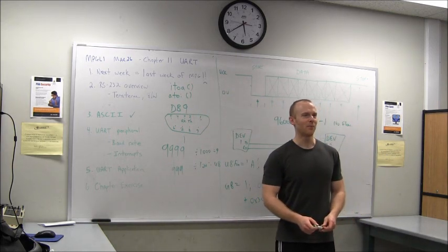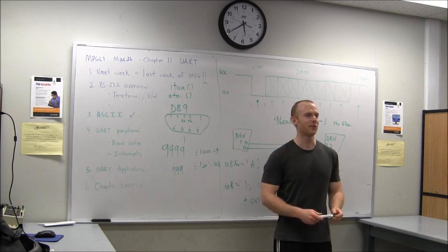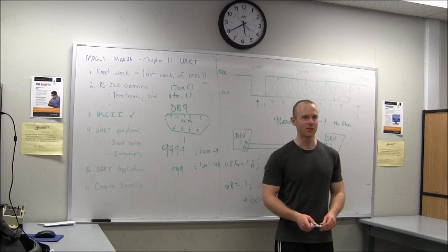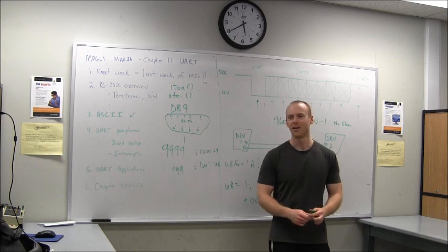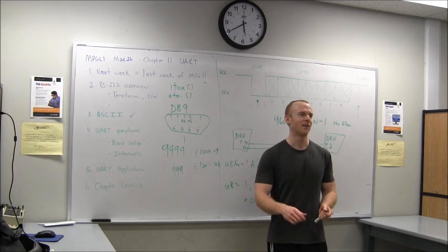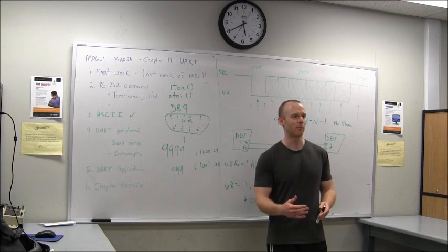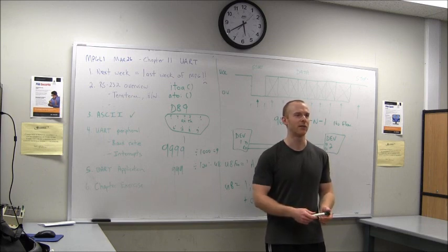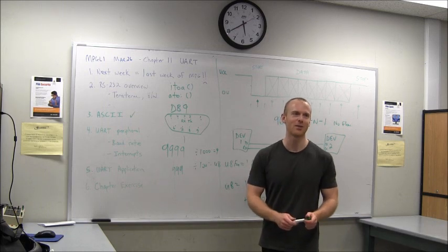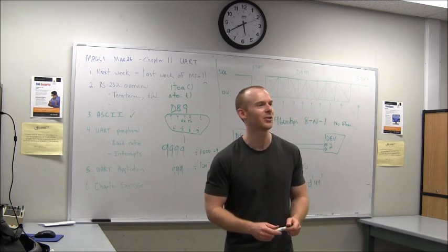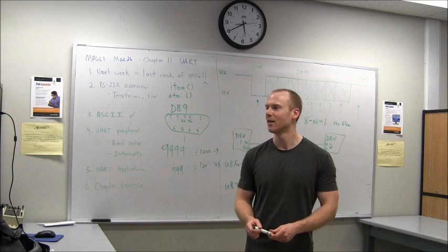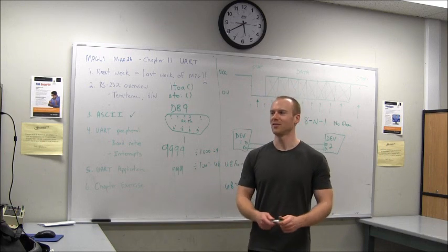Any questions about UART/RS-232? I guarantee you that you will use this in industry because everything has a UART. Even the iPhone has a UART interface out the cable. Every device I've ever done, even if it's not meant as a main function for UART, it'll have programmer's access via UART. Even if it ends up that you're soldering wires on 2 special locations on the board, it's probably going to be there. So get to know it.